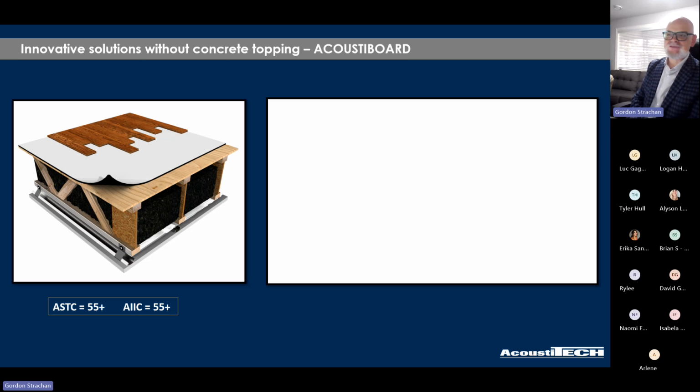Okay, so literally cutting through the polyester felt with an X-Acto knife. Brings it over to the edge, breaks the seam, cuts the rubber at the bottom. Boom, it's cut to size. When I say it's that easy, it is that easy. He's going to leave a small gap between the wall to put some acoustic caulking later, but he's going to walk away.